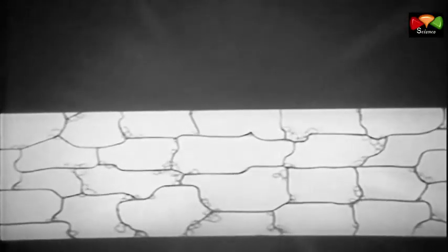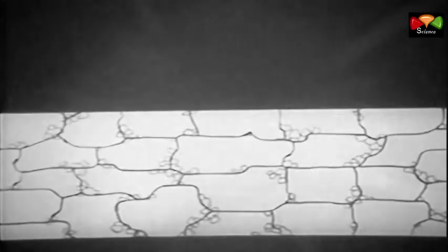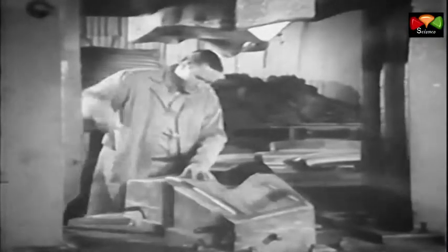The cold working involved in the hammering, hydro press forming, drop hammering, and deep drawing operations results in grain rotation and elongation. But since the plastic deformation is generally more severe, fragmentation and crushing of the grains also occur. The fact that severe cold working results from such operations as drop hammering and deep drawing gives rise to the need for an annealing or softening process between blows or other forming operations in order to prevent rupture of the parts.